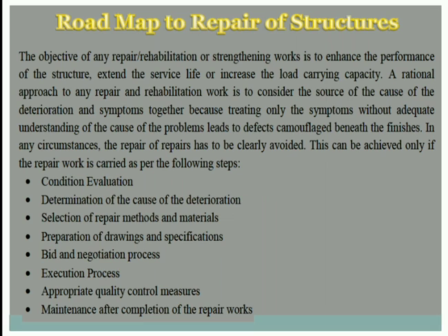Without identifying the cause, if we go ahead with the repair or rehabilitation, it might happen that in the near future the same cause can again come up, which might be the reason for refailure of the repaired structure. So identifying the cause of defect or deterioration is very important.